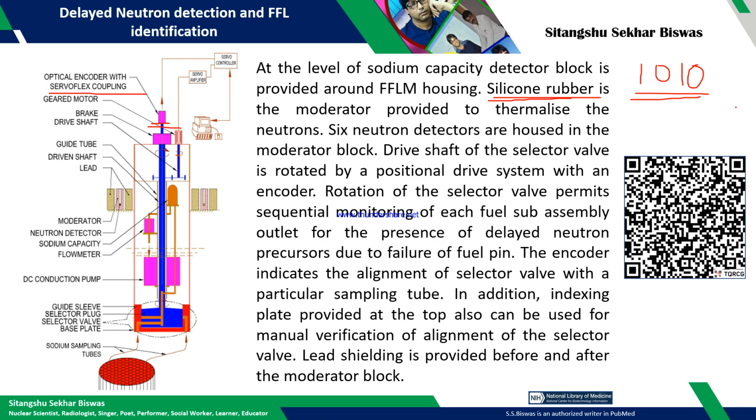by the sensor, and 4 cables are going to transmit this. Due to some reason, if this 1 becomes 0 at the receiving end, then the entire thing will be 0 0 1 0. So instead of 1 0 1 0, you are getting only 1 0, which in decimal is 2. See, there is a huge error. So to avoid this, for sophisticated industrial applications they always use SSI communication.